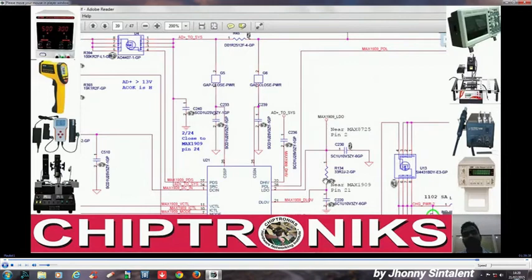In the next class I will be covering the section after this. I would cover the IO controller and ACPI. I'll first have a theoretical class on ACPI, and then I would cover the important aspects of the IO controller, because the IO controller is at the center of power management. And I'll cover another schematic and data sheet, that is ISL88731, which is very similar to this, because the board which we are referring to, Lenovo Y570 or 470, has ISL88731. So let's open the 88731 data sheet.